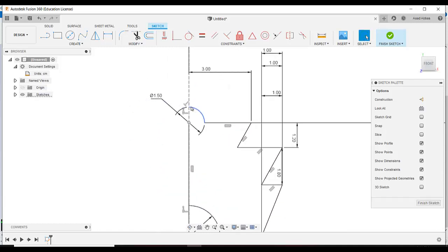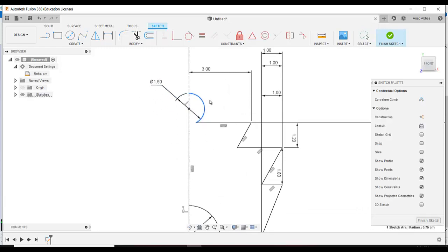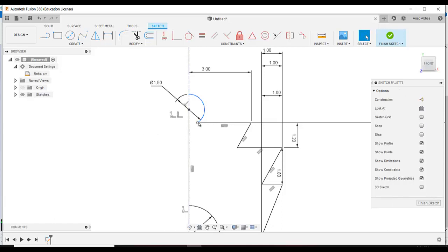And as you know, this sketch has turned blue, so that means it is in that form. It's showing that when you move that circle, it will stay in that form. So we needed to make this point, the center point of that arc or circle, and this point where that circle is ending, have a horizontal relation between them. So these 2 points must be on a horizontal line. So I'm going to select this line, this point and this point, and a horizontal relation is added between them.